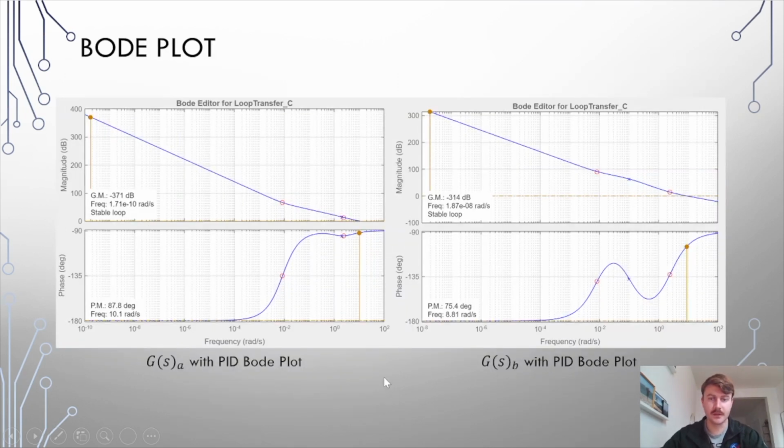And so here are the Bode plots for each of these different transfer functions. You can see that, again, the first version is probably the better estimate of the ratio between the drag and the moment of inertia, which didn't make sense at first, but after a little bit of analysis, it made sense that because the quadcopter frame is already mostly stable to start with, the element that would affect any change more would be the drag of those rotors versus the actual moment of inertia on the center of the axis.